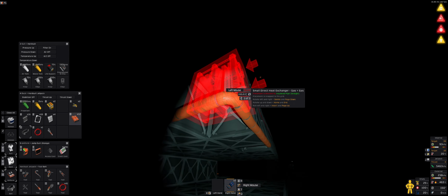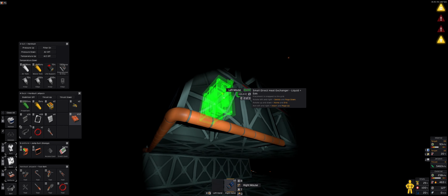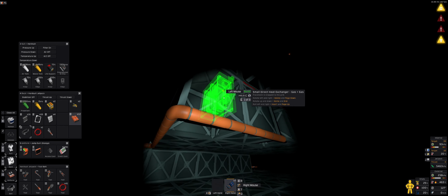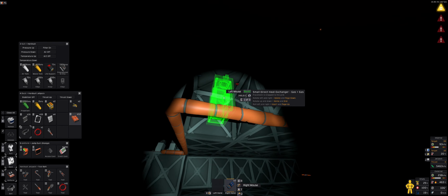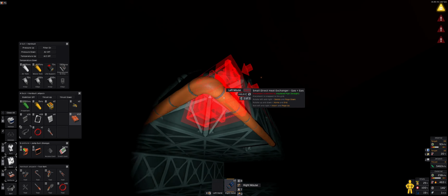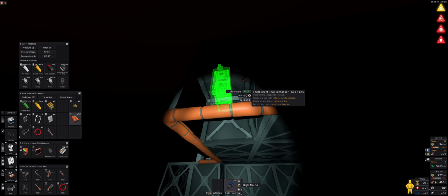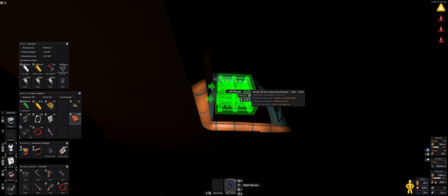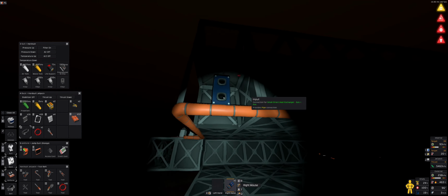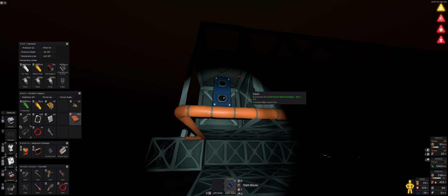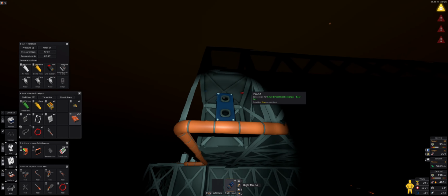The way we're going to do it is using the direct heat exchanger. If you've never used them, they have two inputs. They don't mix the gases, and there is a version for gas-liquid, liquid-liquid, and gas-gas. We're going to use gas-gas. They just equalize the temperature within them, and we're going to add them into this frame. I don't know if they need to be put into a frame, but I always put them in like this. So you have this pipe above the edge, and then there's one break, and there will be another one over here.